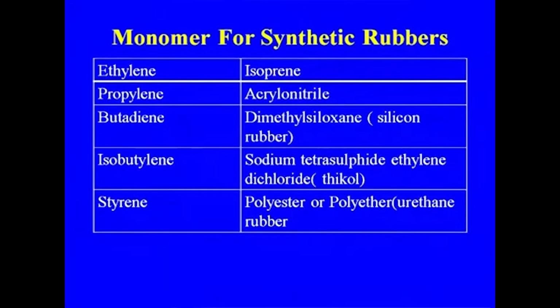These are some of the monomers that we are using: ethylene, propylene, butadiene, isobutylene. So, these are all products we are getting through petrochemicals, isobutylene also. While discussing C4 I told you about MTBE, and that can be cracked, or by hydration, that was another route. So, we will be getting the isobutylene, and for rubber grade polymerization we get high purity isobutylene from the cracker plant, or it may be from the C4 stream of the cracker plant or the FCC.